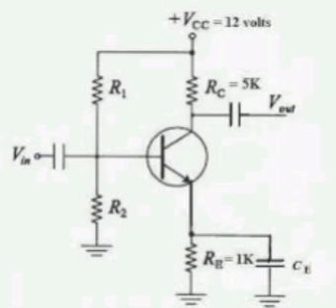R2 equal to (VBE1 minus VBE2) by I naught. VBE1 means VT natural log IR by IS, minus VT natural log I naught by IS, whole by I naught. So R2 equal to VT natural log (IR by I naught) whole by I naught. So 0.026 natural log (1 into 10 power minus 3 by 5 into 10 power minus 6) whole by 5 into 10 power minus 6. So R2 equal to 27.55 kilo ohms.